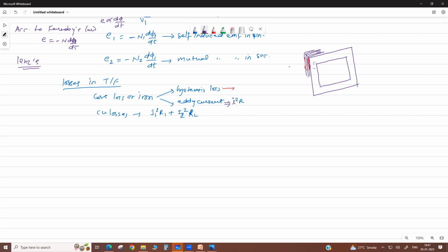So now, laminated. But my dear, here, if we see the cross section area of this core, if we cut, it seems like it may be square type. So the lamination will look like this. When we put a winding over this, this is a square core. There is an air gap. Due to this air gap, there is a leakage flux.